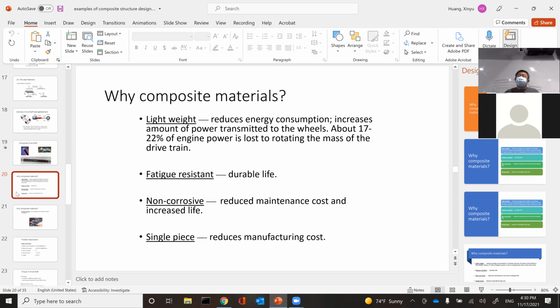General Motors does this. There's a brand called Saturn. Saturn is famous for using lightweight plastic panels on the rear, on your bumper and the rear panels, and the front panels. There's still some metal panels, but those panels are lighter in weight, and they have advantages. They don't rust, and if you dent them, they actually bounce back. You can punch them, they cave in, and they push out. They're kind of elastic.